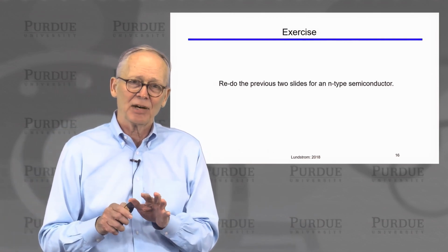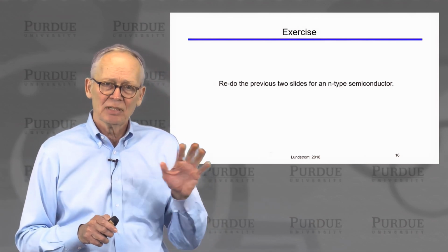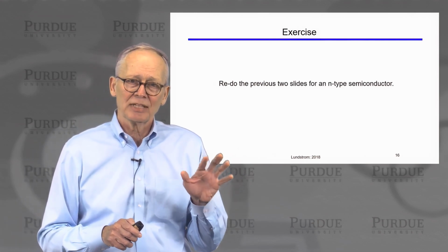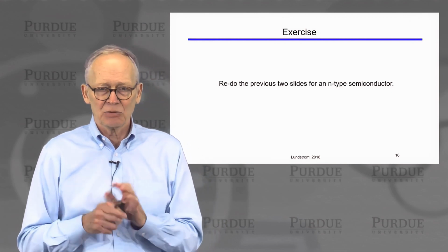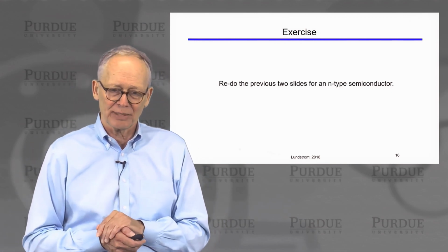As a test for how well you understand those concepts, redo all of those diagrams assuming an N-type substrate, and redo the charge versus surface potential plot.